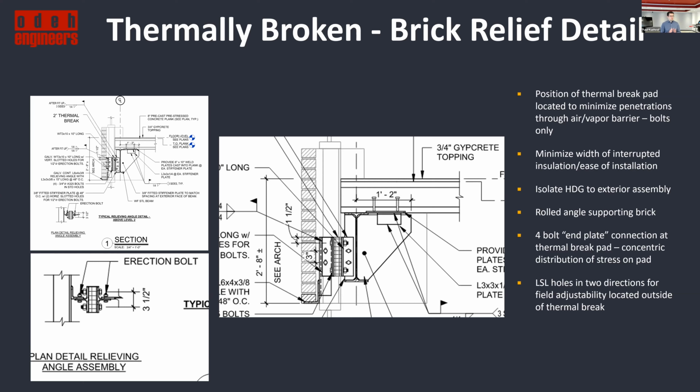It's important to work with your building envelope consultant to address the location of that thermal break pad to ensure, you know, not only the thermal efficiency of the detail, but also the constructability of the detail, where the position of the air vapor barrier is, the exterior sheathing, and so on.